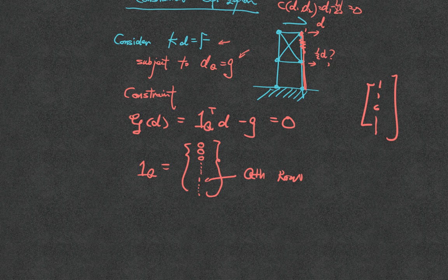For better balancing or for whatever reason, for domain decomposition, you also need to put in this constraint. Do you know what domain decomposition is? You have a big finite element mesh, and you don't want to solve it on one computer, so you cut it into multiple subdomains. But this still requires communication, right? And then you can use Lagrange multipliers or the penalty method to introduce this.